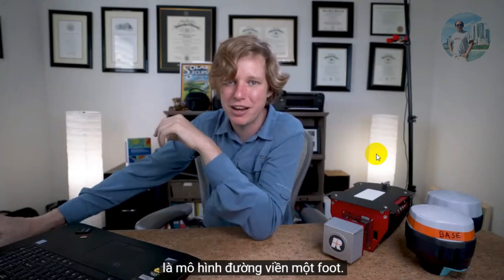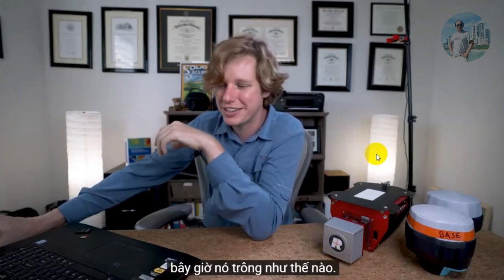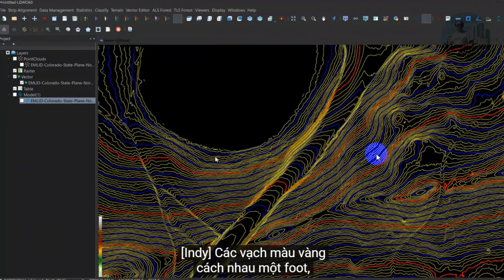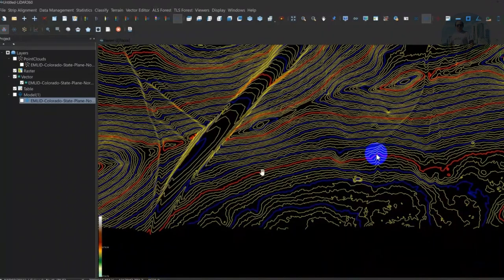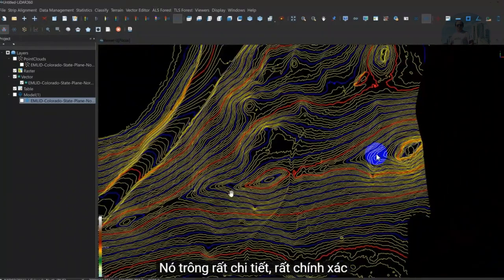Now, the final piece of information we want to derive from this data here is a 1 foot contour model. I'm going to go ahead and show you what that looks like now. The yellow lines are 1 foot intervals, then every 5 feet you see a blue line, and every 25 feet I have a red line. It looks very detailed, very accurate.